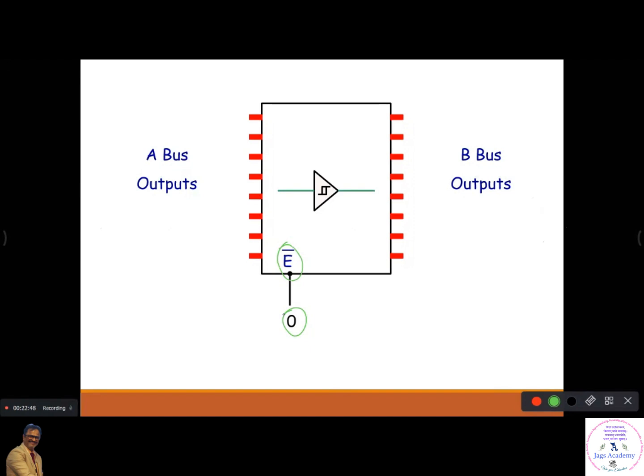That's why whenever you separate the address data bus as a data bus, whatever you use in between should be bidirectional, not unidirectional. That's why we use buffers here. For the time being, just remember it as being like a latch, but it can transfer in both directions: A can transmit to B or B can transmit to A. This is what a buffer is.